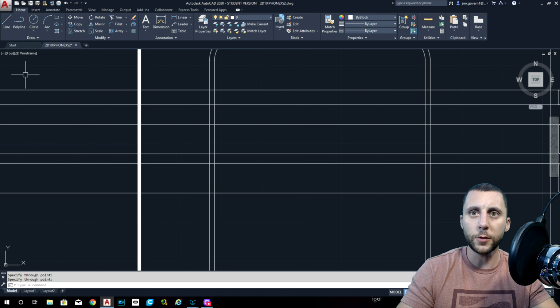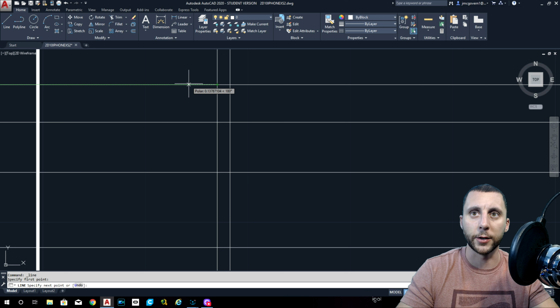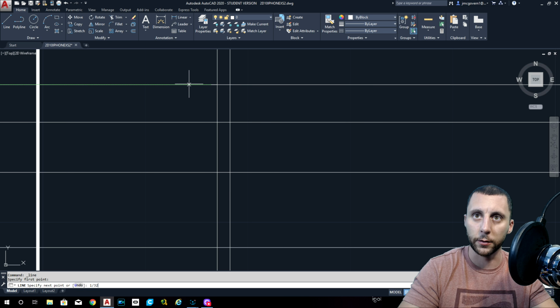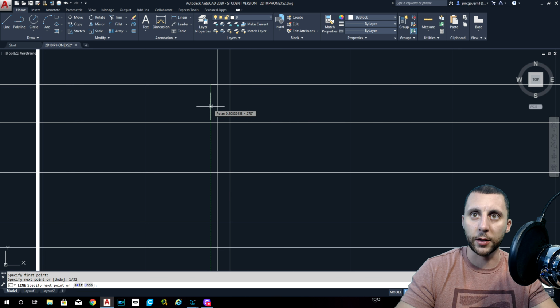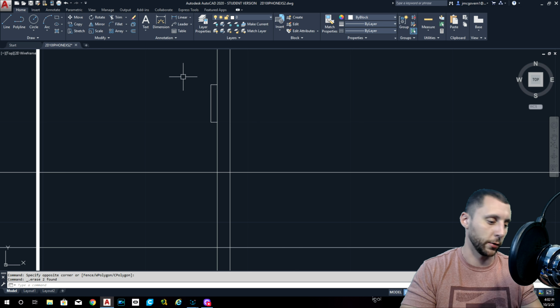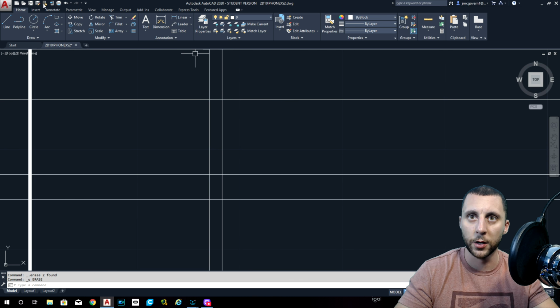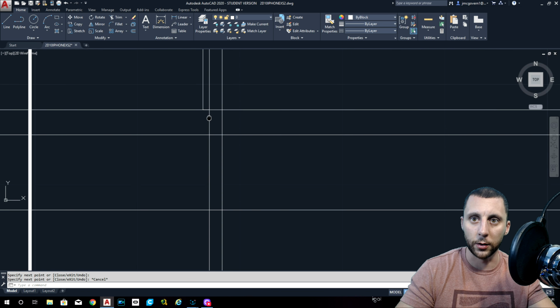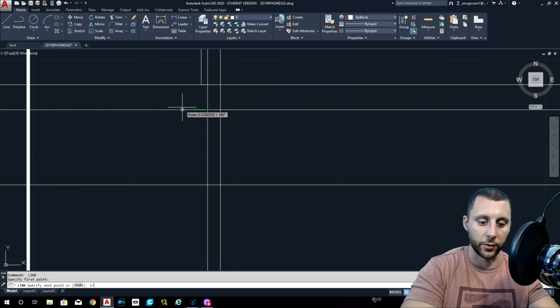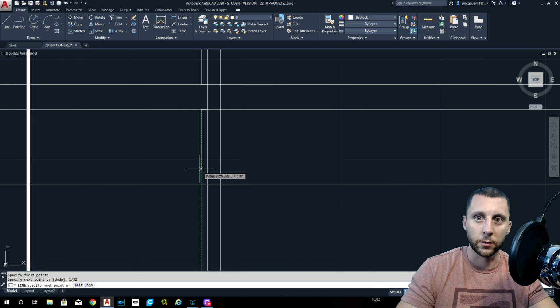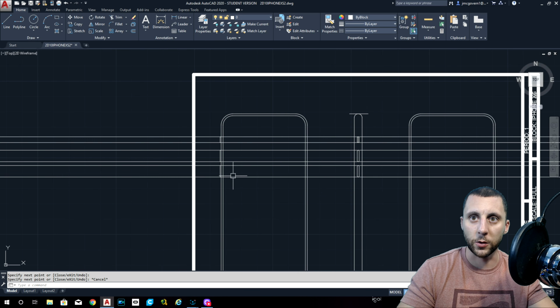So rather than doing all this crazy trimming, I'd probably start here and draw out 1/32, and that's behind that big line now. Then come down and then go in. If I were to erase these, you would have that button there. But don't do that yet because we need them on the far side. So we're going to do the same thing for each button. Start here, go out 1/32, go down, and then go in. Out 1/32, down, in. All right, so those three are done.